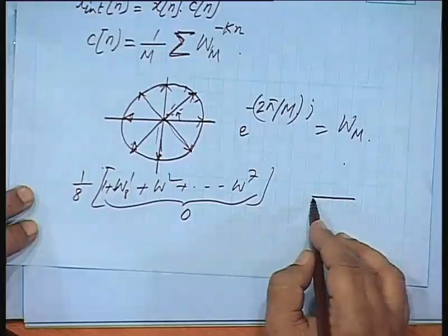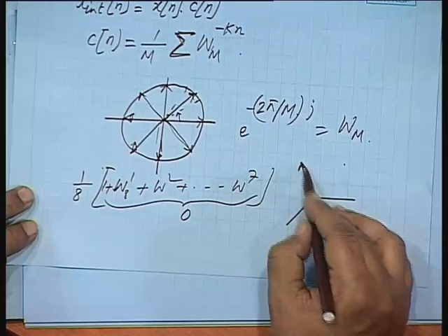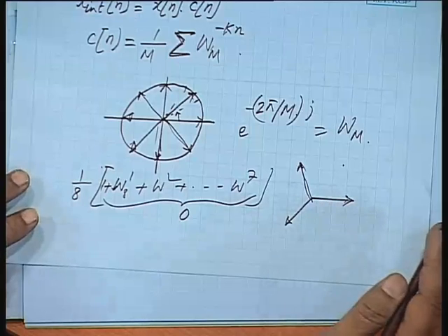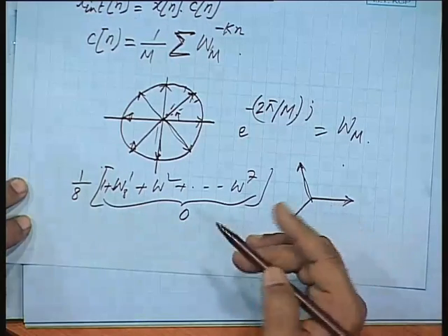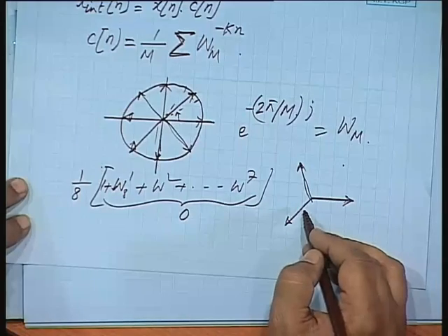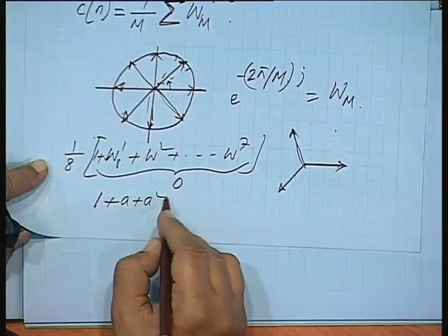This is precisely what I was discussing earlier, this is precisely what you get in case of positive sequence, negative sequence components in a 3-phase system. If the system is balanced, then what you get is only 1, and when you multiply by alpha square of that balanced set, you get 0, okay. So, you get these terms, is it not? 1 plus a square is equal to 0.